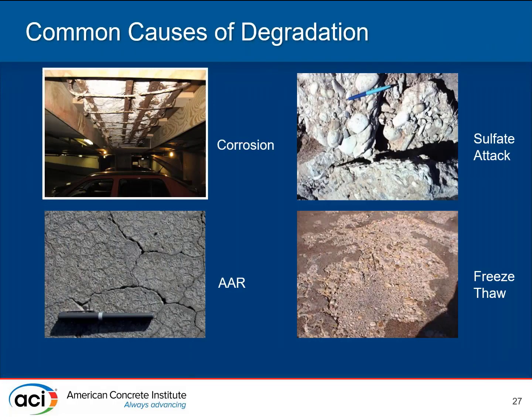And just to further get on those things here, just some quick examples of some common deterioration that you see. This isn't an exhaustive list. I may have mentioned some other ones earlier, but these are the ones that people are certainly familiar with. If you've ever done a repair, or ever walked into an old parking structure in a de-icing zone, or on a wharf in the sea, you're going to have seen corrosion of the steel, causing the surface to pop off.